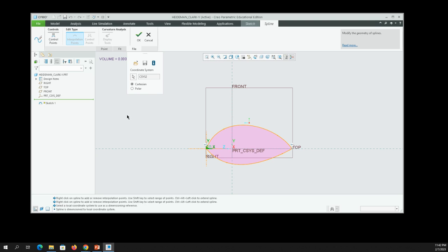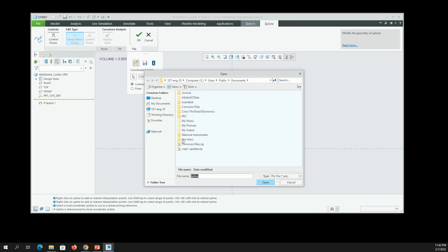And so there's my coordinate system. I want to load my file. So I'm going to click read points from the file. It looks like a little file open icon. I'm going to go into my downloads directory where I had these. I had selected the upper set of points, so I'm going to click the upper set of points here, and I'm going to click import.